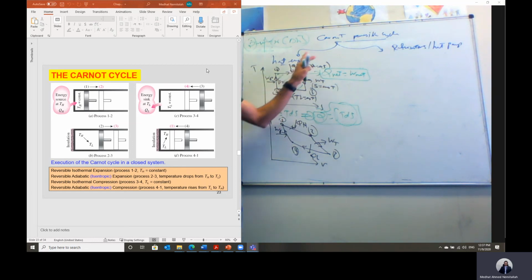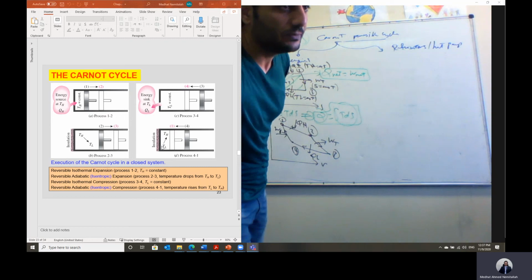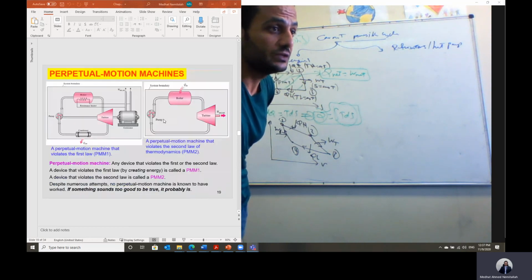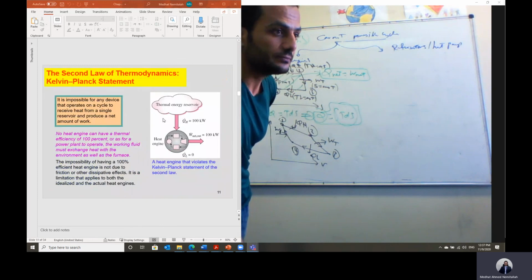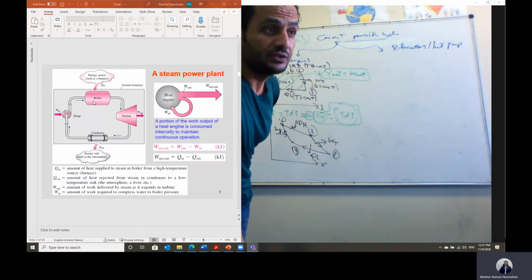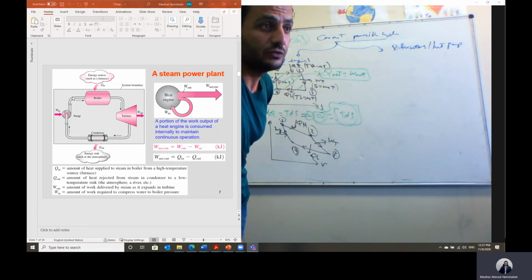This cycle, the Carnot cycle, can be applied for heat engine and refrigeration cycle, for open system and for closed system. As I told you, in case of heat pump cycle, in case of heat engine cycle, here is the cycle. This is for a heat engine. We said heat is added here. I can give you the condition at the inlet and the outlet, then we can calculate Q high. But we apply the first law of thermodynamics for a steady flow open system device in this case.